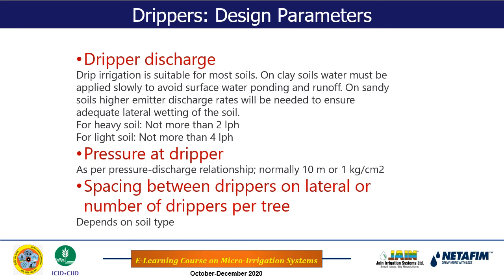Now, when some of the water builds up on the soil surface, then because we adopt the drip irrigation method on rolling topography, there may be certain slopes within the smaller area as well. As head builds up because of the ponding, the water will move from the tree rows or crop rows into the drier area, and that area will be wetted unnecessarily.